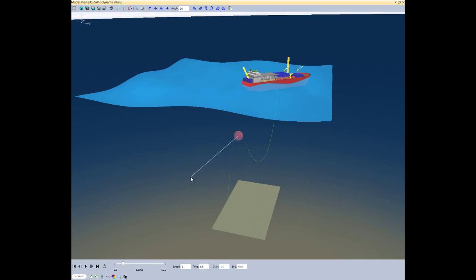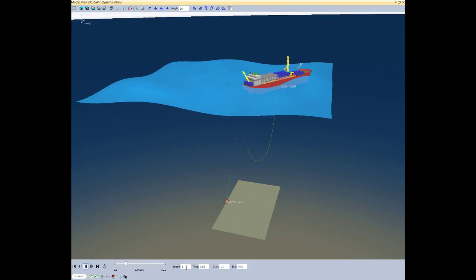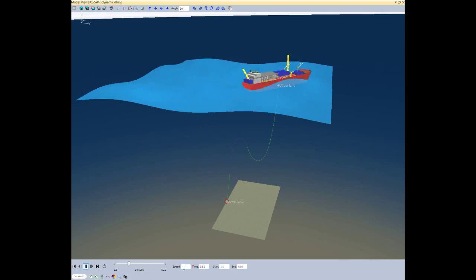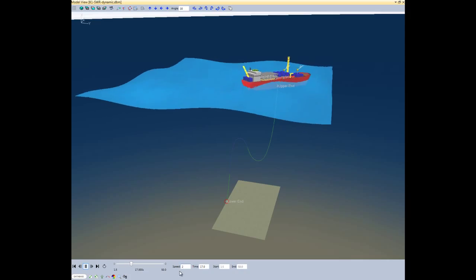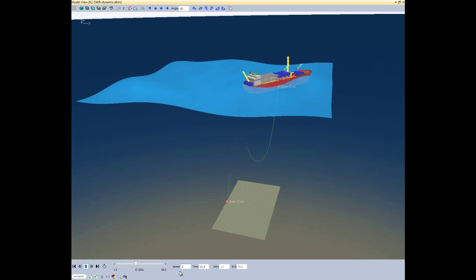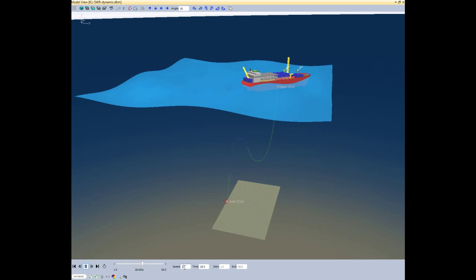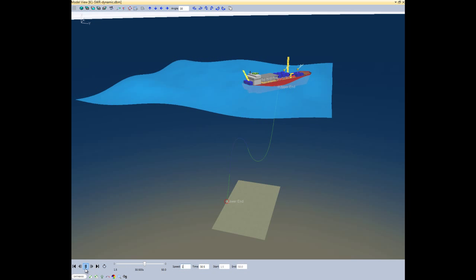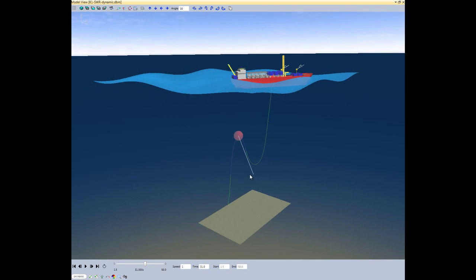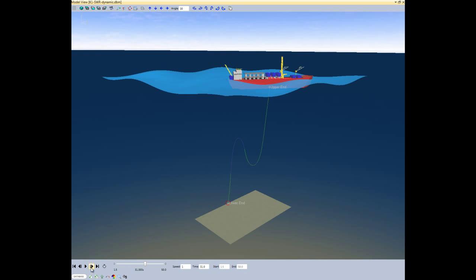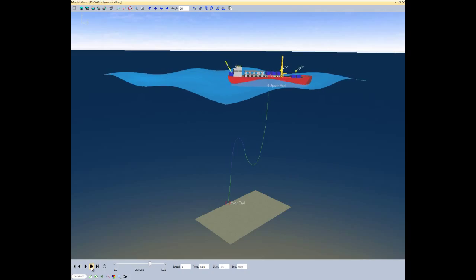The model may be rotated by left-clicking on the screen, holding the mouse button, and then dragging the mouse. The area of interest should first be placed in the center of the screen using the arrow keys, or panning with the mouse. In order to ensure a smooth rotation, you should click near one of the screen edges and drag the mouse in a straight line towards the other side of the screen.